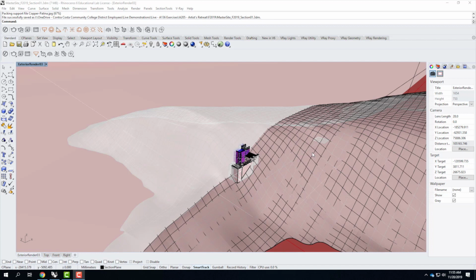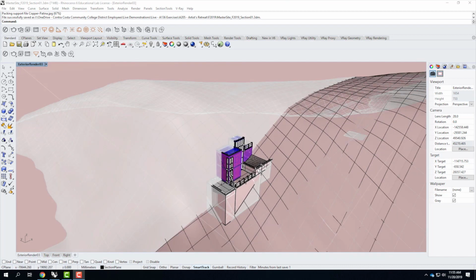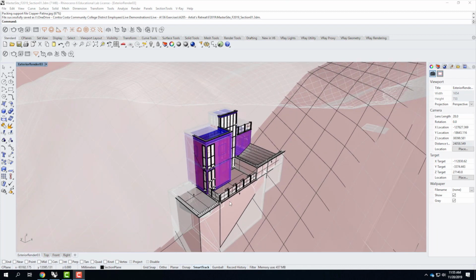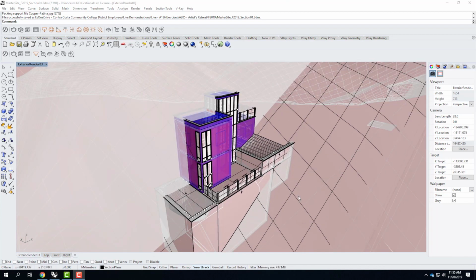And I think if you can master this skill set, it will serve you really well down the road. One of the problems with many 3D modeling programs, including SketchUp or Rhino, is if you set up a temporary clipping plane, when you go to render it, you get a rendering where that half of the building that's clipped off is wide open.